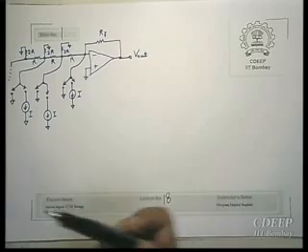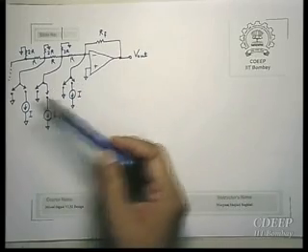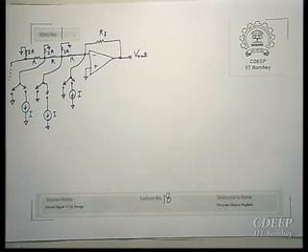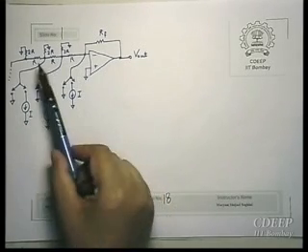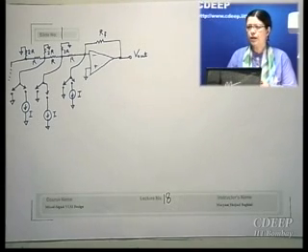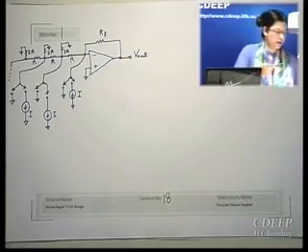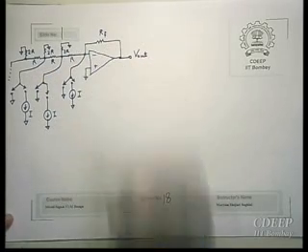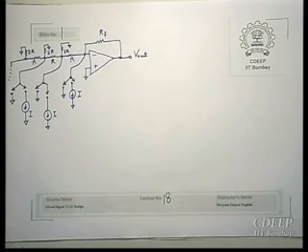So the benefit is that here you will get a constant current for switches, so you can use the same sizes for all switches. However, internal nodes are still changing. Therefore, here you have the same trade-off. Either you will get different drops across switches, or you will get different voltages on internal nodes. If you want to keep them constant, then you need to resize switches for different bits. If you don't want this scheme or another scheme that we had, then you will have variation of internal nodes. This is just for your information, and it's easy to understand.